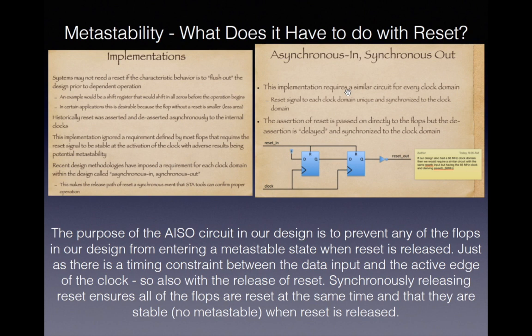It may exhibit metastability because there's no timing relationship between the release of that reset and the clock. If it does, it'll settle in less than one clock period. So the second flop will be clean. When it goes high, the reset out goes low. And what we're doing is synchronously releasing the reset to our circuit.